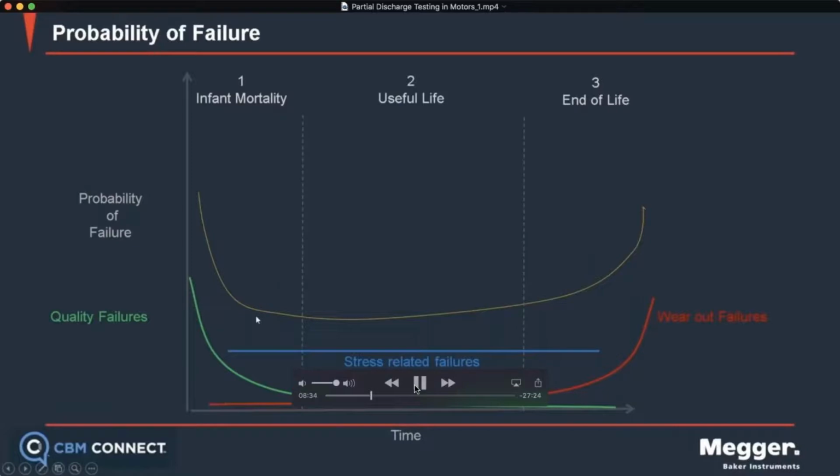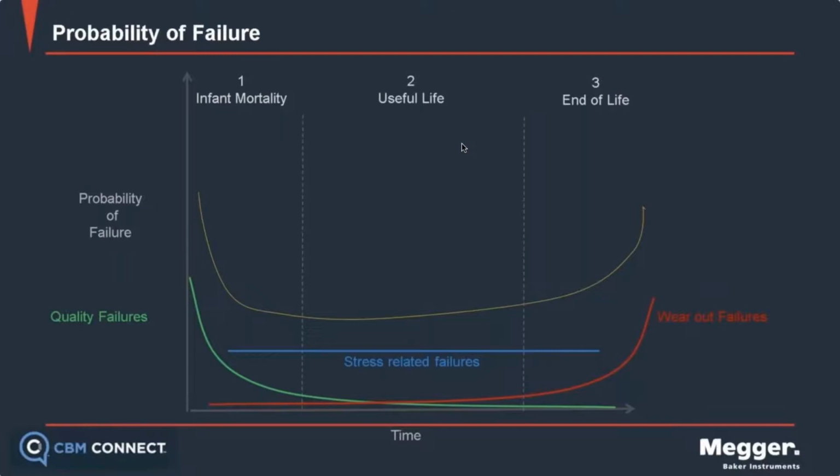And then once we've gotten through that phase, we understand that the probability of failure is low because we have a high quality product. Then we want to look at it over time to see that potential voids are being created because of movement of coils or other internal deterioration of the insulation. If partial discharge activity starts to increase at lower and lower voltages, that would be an indication that we're at least accelerating our degradation and possibly entering an end-of-life condition. So I'll show you later how partial discharge may be a little more predictive than maybe even surge testing is at lower voltages.